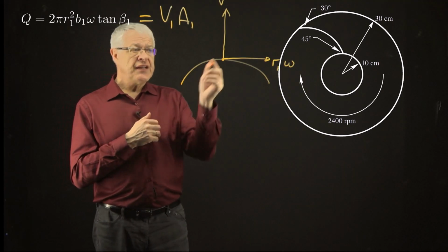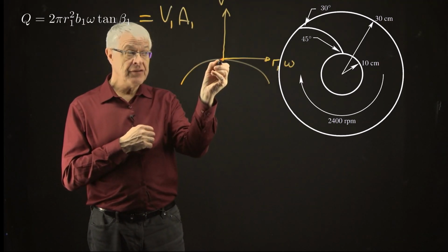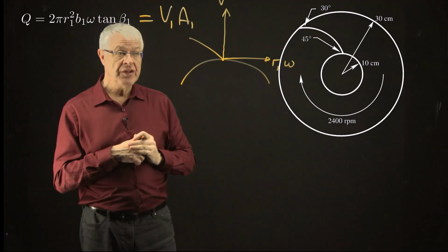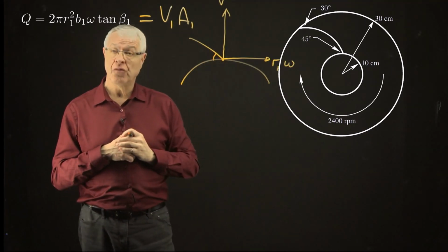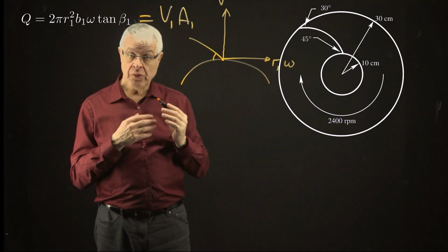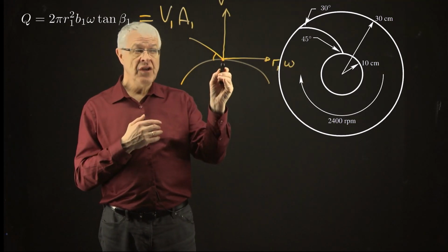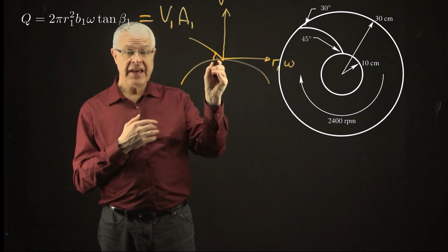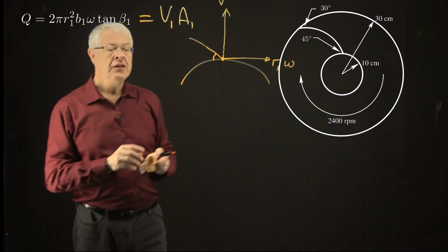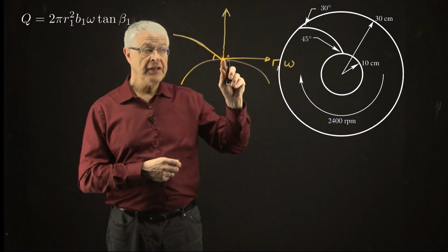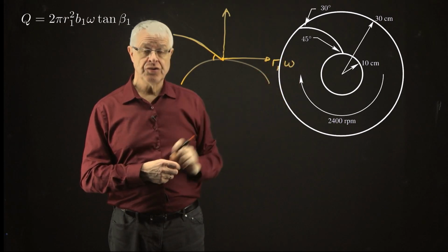So realize that there is an impeller blade here that water needs to engage with. And in this particular problem, that angle there is 45 degrees. So again, for maximum efficiency, the water has to be traveling tangent to that impeller blade relative to the impeller. So the velocity of the impeller blade is r1 omega in that direction.